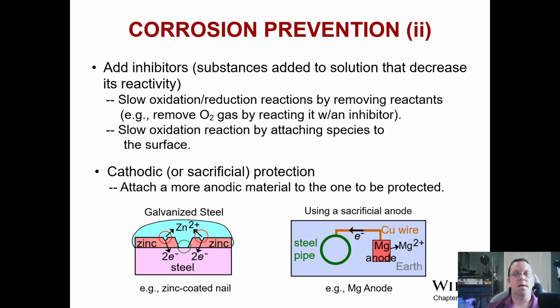So instead, it's cheaper to have these large magnesium anodes that you then are applying a current across. And what you can do is, by holding a current constant in that circumstance, you can protect the underlying steel from actually corroding. So there's a bunch of benefits to those that allow you to maintain function and operation, and prevent your pipeline from prematurely degrading. It's just something that has to be watched pretty closely.